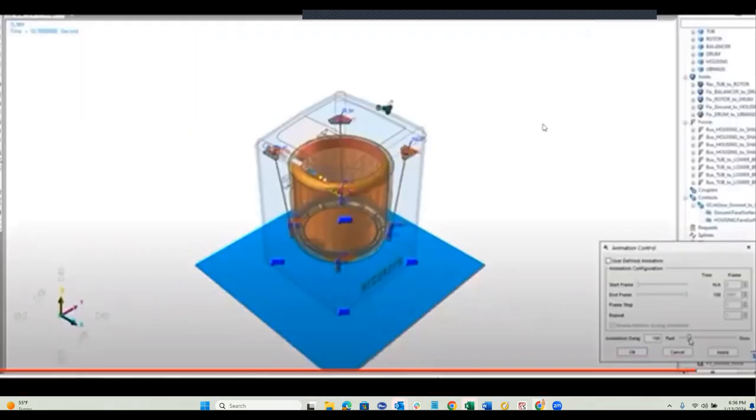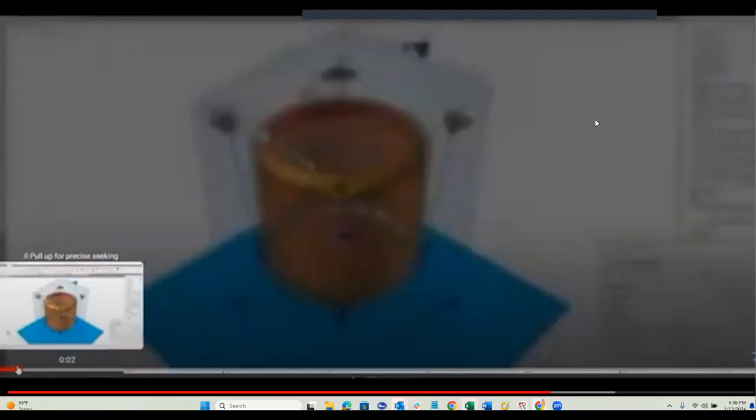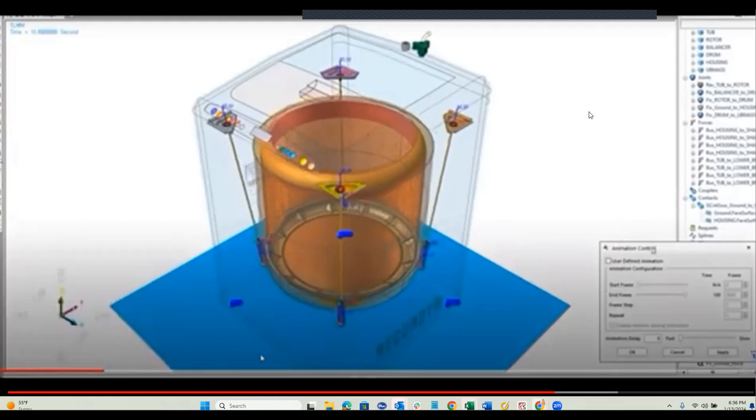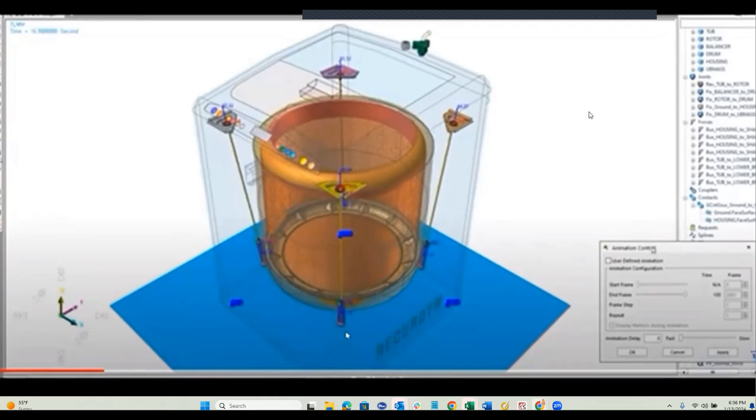So we have the model wherein we are seeing the rotating of this machine. You see that this whole drum is being rotated by a motor which is below this. But at the same time, this drum does not perfectly rotate on the vertical axis. When it's rotating, it might have a sidewards motion. These springs absorb that sideward motion. You need to realize that. And when such a thing happens, it is going to have a vibration. That is the vibration we're going to measure here.